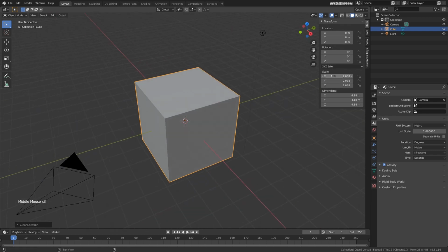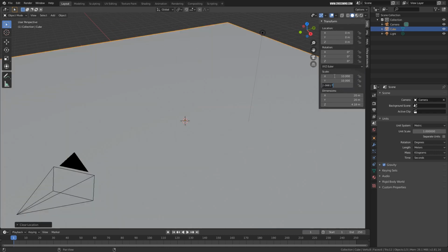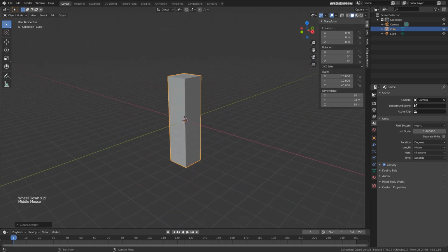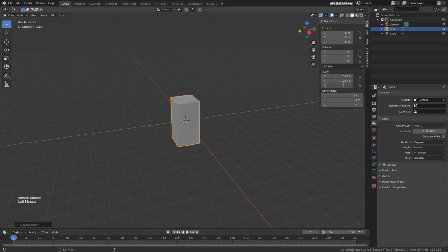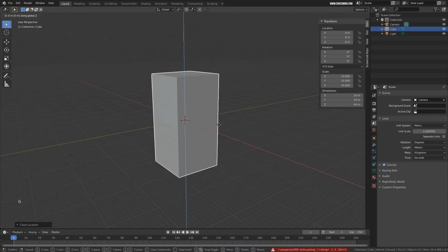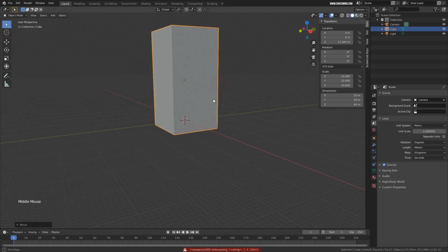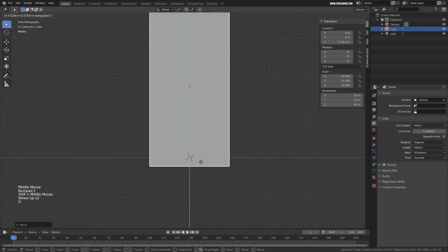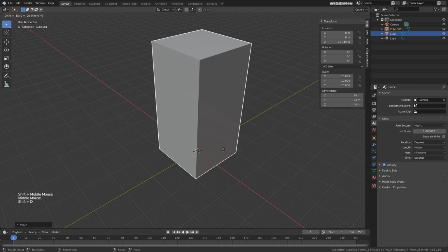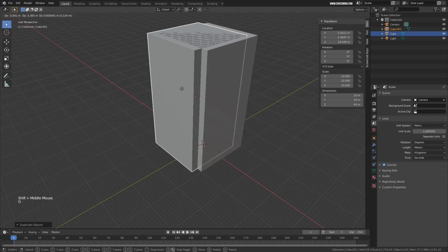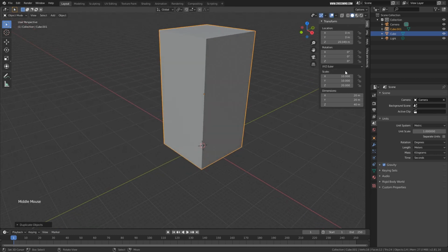Let's say I want this building to be something like 10 meters by 10 meters and 40 meters. Okay, let's zoom out. Maybe not 40 meters, 20 meters, right? I'm going to press G and Z so that we can move this right above the grid. Then I'll press Shift D to make a duplicate of it, and right click to cancel the command so that we have the duplicate right over the building. Now this one I want to be something like the ground. It could be just 0.2 meters.